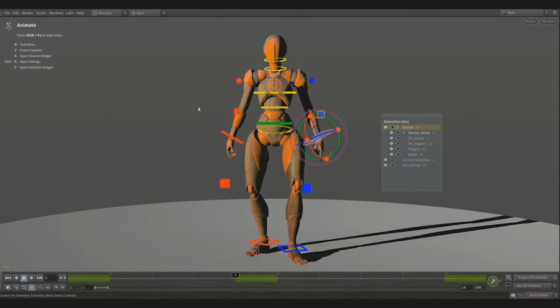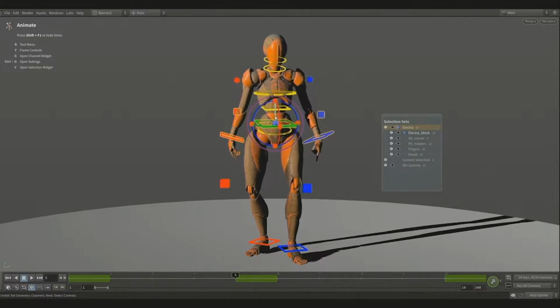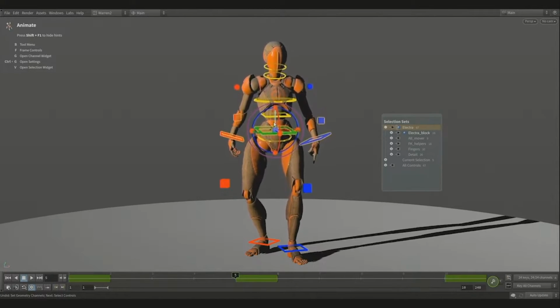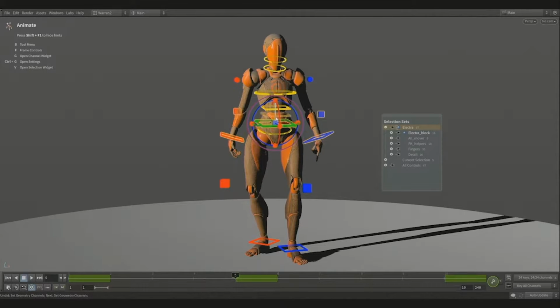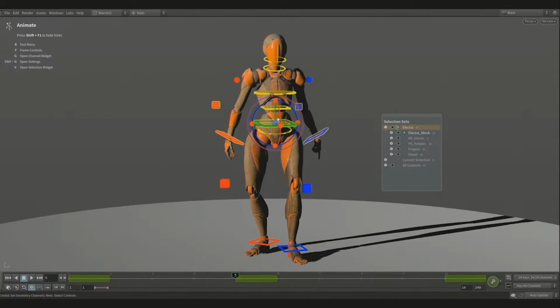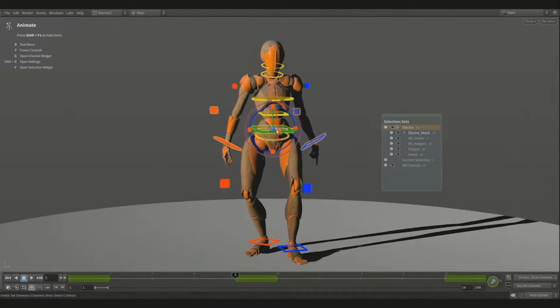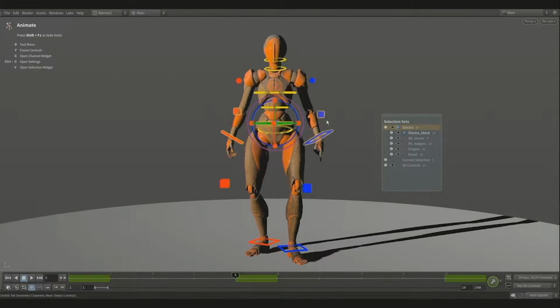The other thing we have is this control shift control. Typically when you grab joints and rotate them, they'll just rotate around their centers. But with the click control, you can determine where the pivot is for multiple objects.